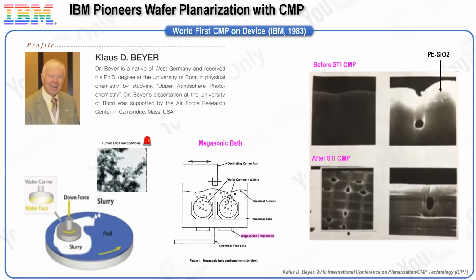His determination was evident when he observed a trench isolation test wafer displaying a uniform green color without surface scratches, unlike other qualification bare silicon wafers. This observation was a beacon of hope amidst his concerns about the cleanliness and acceptability of the CMP process for device integration. It is important to note that random holes observed in trench areas within the SEM image were due to inadequate glass wetting in trenches measuring 1.5 micrometers in width after the reflow process of lead silicon oxide.